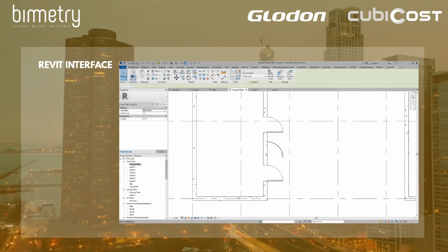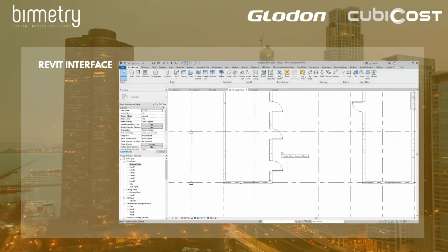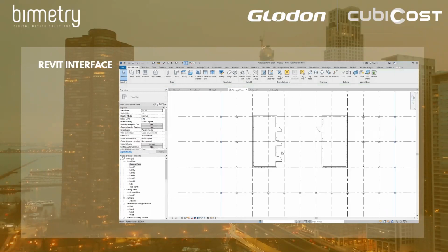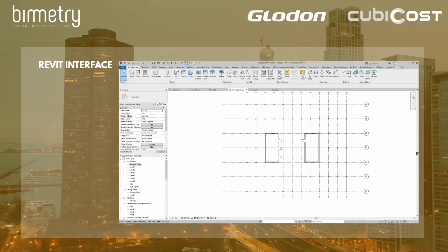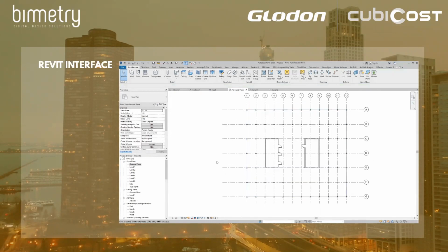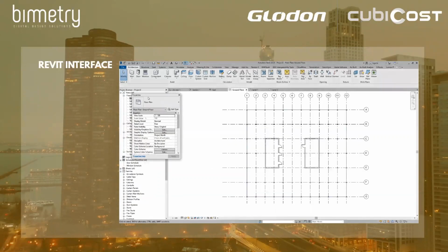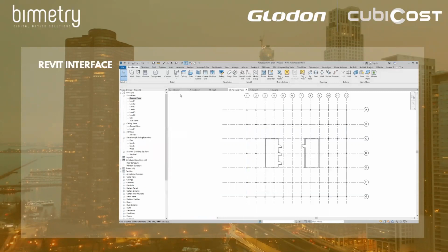If you have a lot of metadata, you would immediately see. You just saw on the screen 2D lines that were following the contour of a door, but weren't actually a real door. This is something to be mindful of. A lot of designers sometimes use 2D lines to do their drawings, but don't draw the object, or they don't load the object.